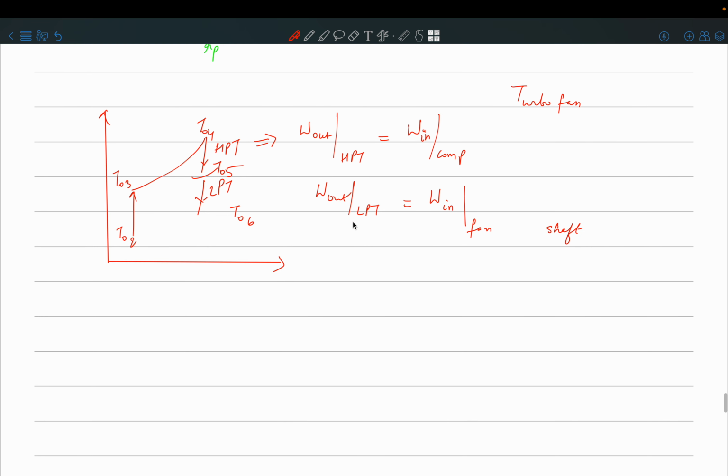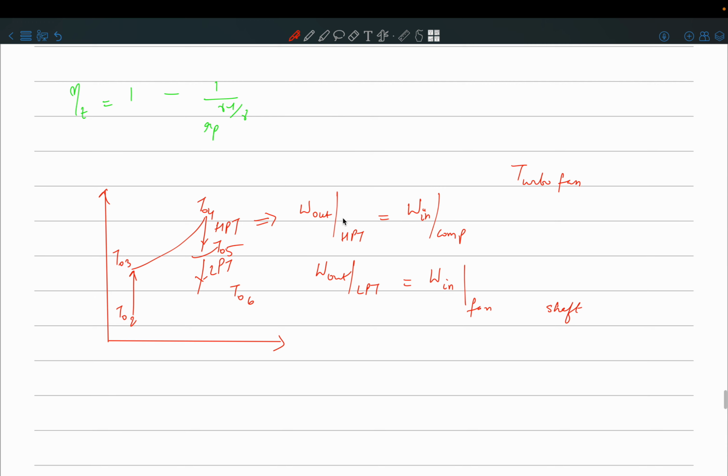So that you have to use over here. Okay, and from that, say this was again ideal, then you can find the pressure ratios using the adiabatic relations. Otherwise they will give an efficiency per turbine, efficiency of the high pressure turbine, efficiency of the low pressure turbine, and then you can calculate like we did in the last question. Okay.